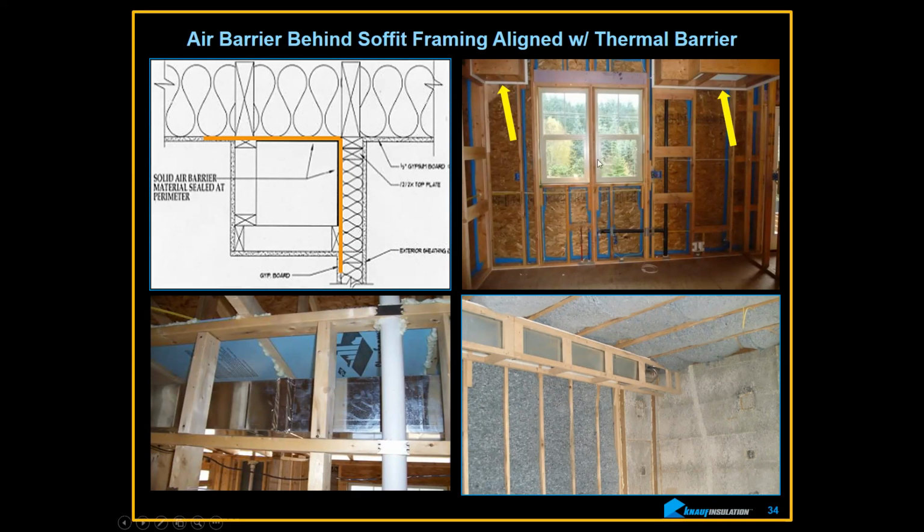So the best way to do it is to have a little bit of your drywall hang down before you put your soffit up. And that way the drywaller comes in with his wall, with his panel, he can go right up to the top. It's got a tapered edge. He seals it right off, muds it, he's done.